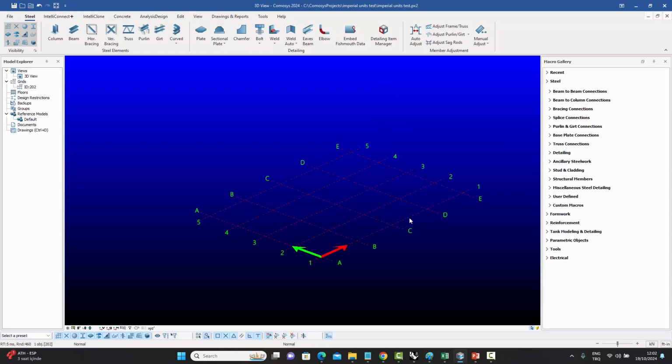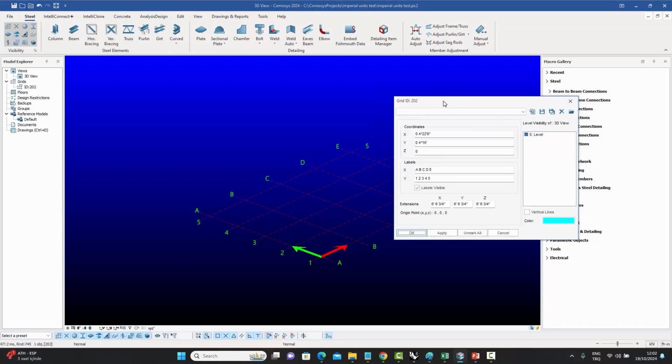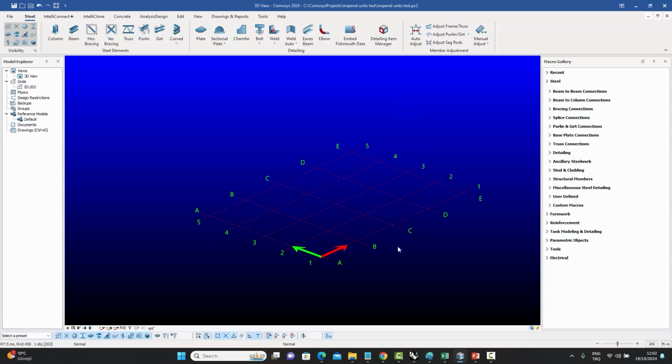So it's 22.5 feet right now. If I wanted to say 6 and 3/8 of an inch, in that case I would put the underscore sign and say 3 divided by 8 of an inch. That would move it slightly more. So this is a convenient way of inputting your distances in the feet-inch format.